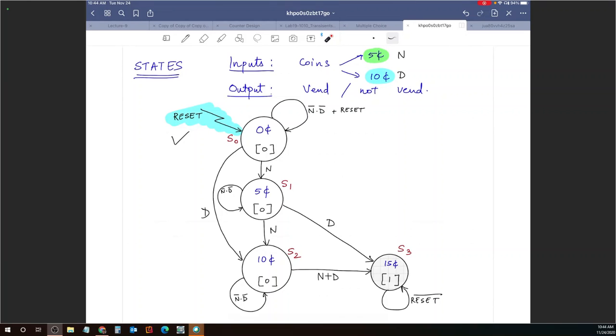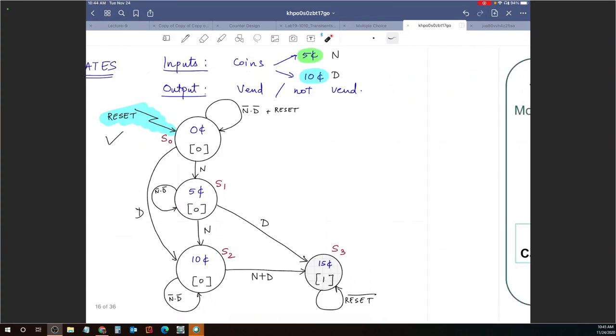I'm not sure if it is valid, if you can do that for this particular finite state machine, but for other finite state machines, you can certainly spend some time thinking about how do you reduce or minimize the number of states, because that is directly linked to the number of flip-flops you would need to implement that finite state machine. All right, let's move on here.